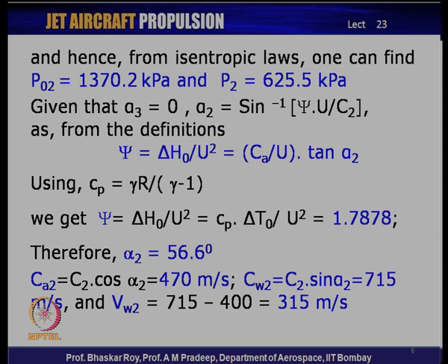The higher this number is, the higher the stage is being asked to perform, and so keeping an eye on this number tells you whether the stage has been sufficiently loaded or the stage loading has been maximized. And in case of aircraft gas turbine engines, as we have discussed before, we would like to maximize this number without causing undue gas dynamic or structural problems.